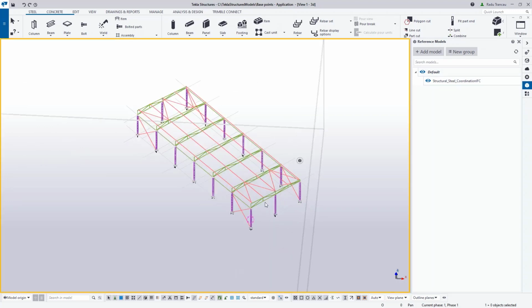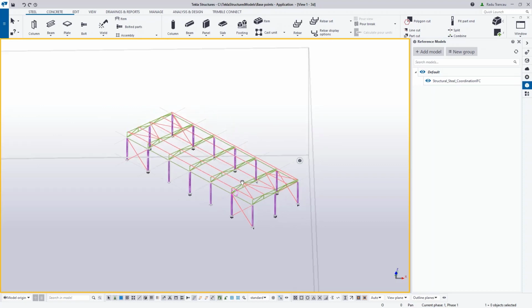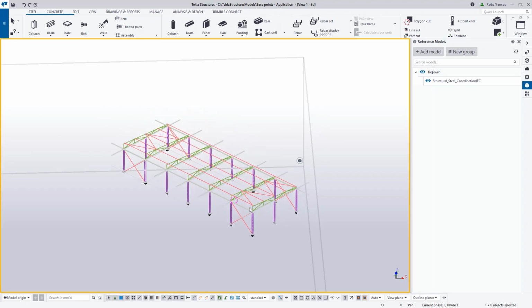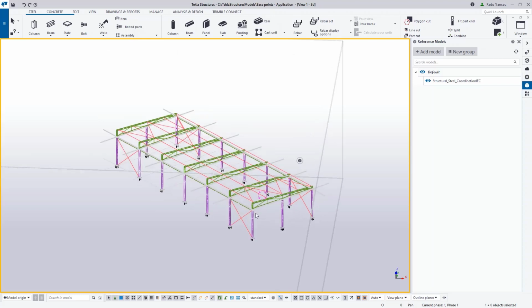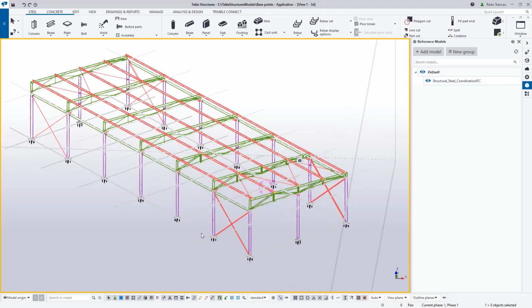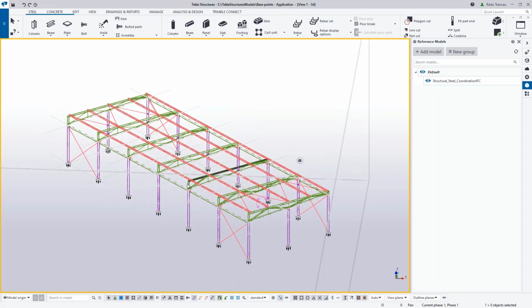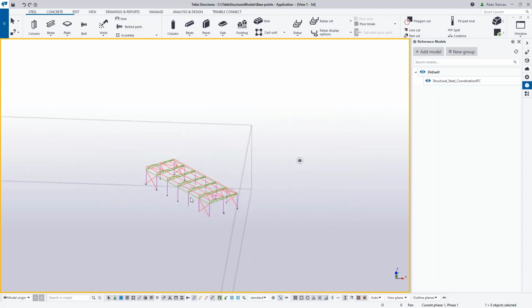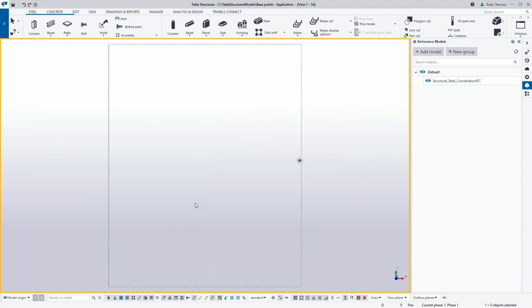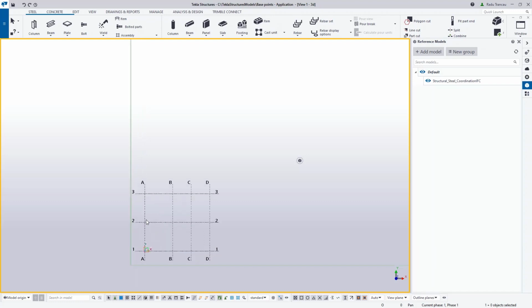We will be looking at three options to do that. And before bringing the IFC back to the origin, we will be talking about the reason why we want to do that. It is recommended that you model in Tekla as close as possible to the model origin. Why is that? Is because Tekla does lose accuracy when snapping and modeling, and also when you will start creating drawings if you are far away from the origin. So that's one main purpose for using base points.